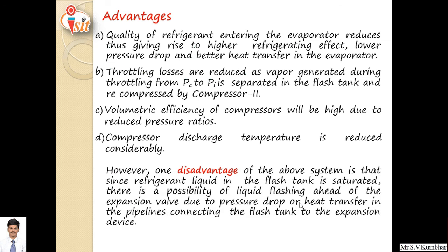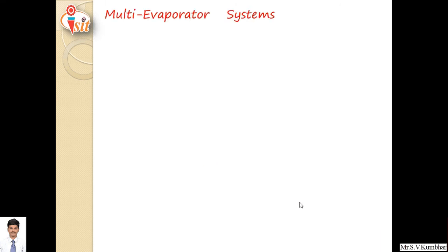However, there is one big disadvantage: since the refrigerant liquid in the flash tank is saturated, there is a possibility of liquid flashing ahead of the expansion valve due to pressure drop or heat transfer in the pipeline connecting the flash tank to the expansion device.